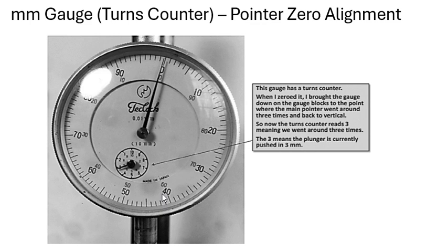Don't feel bad about this technical term. It's just telling you that the contact with the surface is adjusting, and this dial is very sensitive to that contact with the surface. So it goes around in order for us to find the balance. The pointer rises and falls, meaning that this dial indicator is trying to balance itself.